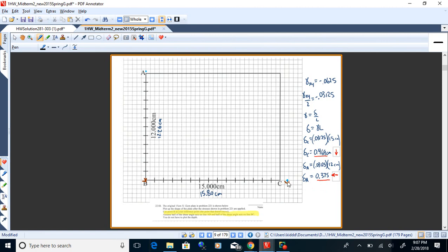So I'm placing that dot about 1.6 boxes, which if each box is half a centimeter is 0.8 centimeters out from the original position of C. Similarly, I'm moving A up a little bit to signify the 0.26 elongation there. So I'm moving A up and C out, and I'm moving them proportionally in amount to signify these deltas: 0.8 for C, 0.26 for A.